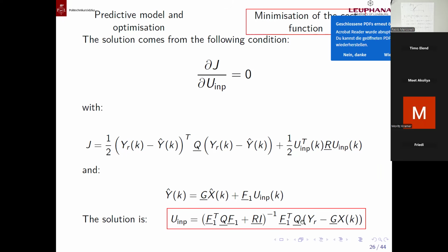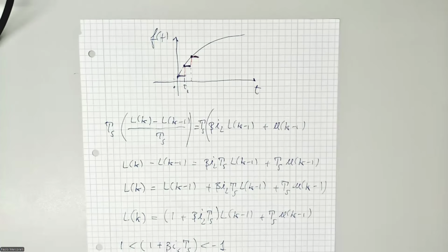we don't need a solver. We don't need PSO. PSO isn't a solver, remember I told you. Or other kinds of solvers. We will see this next week, and then we will, in any case, simulate the basic form of MPC through MATLAB. I will come back to these block diagrams, and to the concept that we have to measure or to know somehow, using an observer, the actual states, xk.